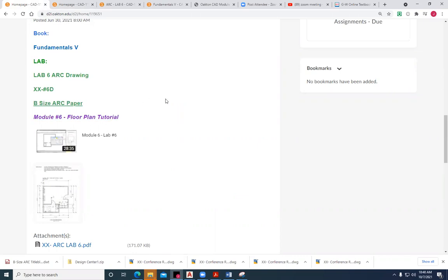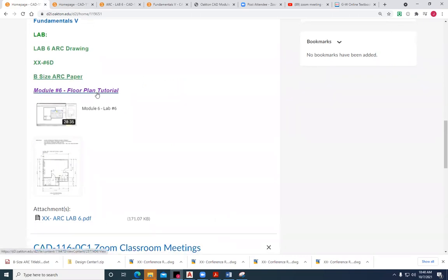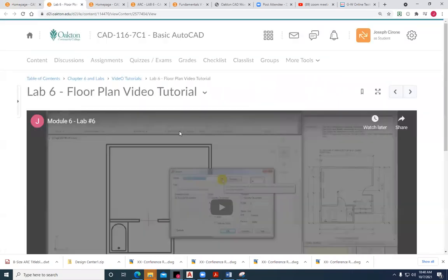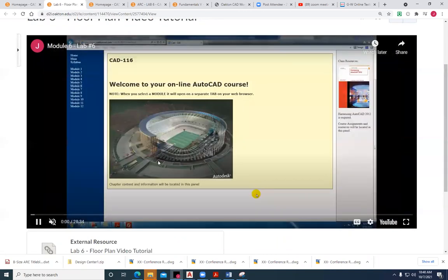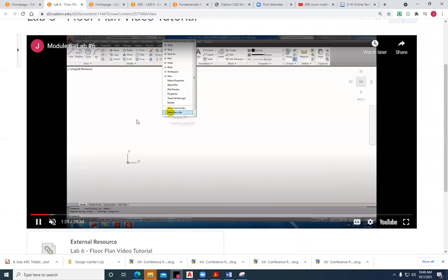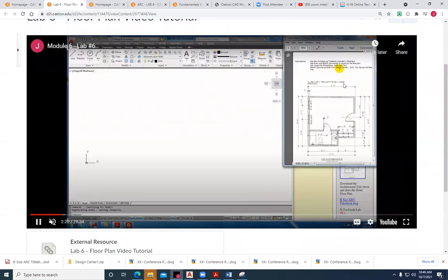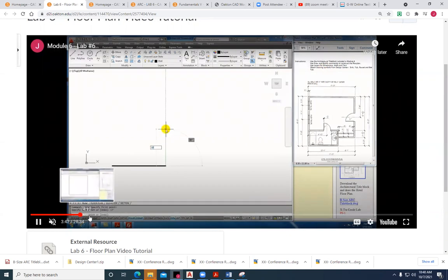That's all right. And then here's our tutorial. This is a well-made tutorial. It goes through all the detailing aspects of working with this exercise. It is a little bit dated because we're pre-D2L. As we look at how this is created, we go through a lot of the same applications where we'll show the menu bar, we'll bring up our curriculum, and then we'll go through and start drafting the walls using direct distance measurements, 17 feet.